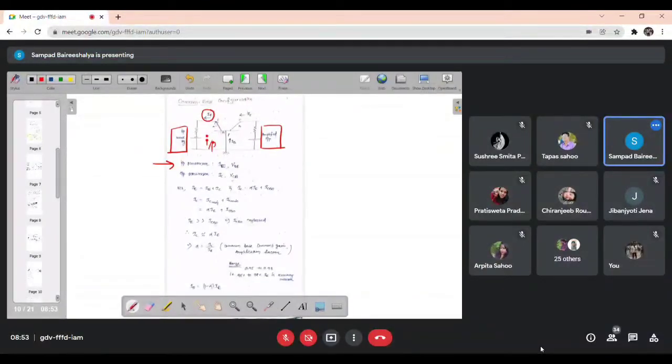Yes, sir. And if you look at your output side, your output current is IC and your output voltage is the voltage between collector and base, that is VCB. You may ask, sir, why are you writing VCB and not VBC? Because current is flowing from collector to base, so the higher potential is written first, then the lower potential. Is that clear? Yes, sir. That is the output parameter, that is, output current and voltage. Okay, fine.